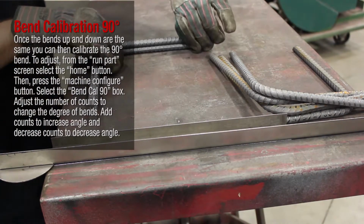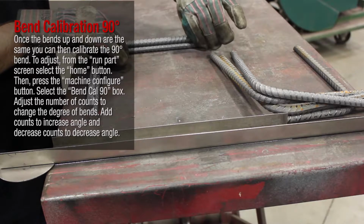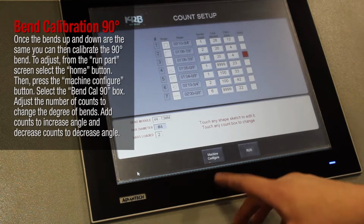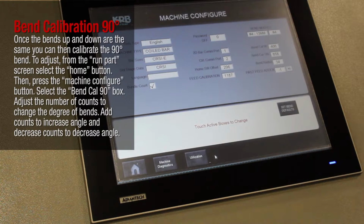Once the bends up and down are the same, you can then calibrate the 90-degree bend. To adjust, from the Run Part screen, select the Home button. Then press the Machine Configure button. Select the Bend Calibration 90 box. Adjust the number of counts to change the degree of bends. Add counts to increase angle and decrease counts to decrease angle until 90 degrees is achieved.